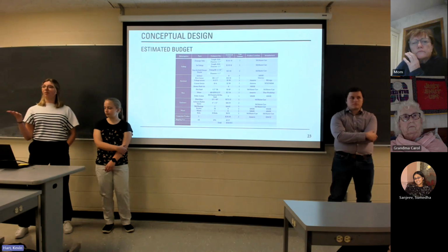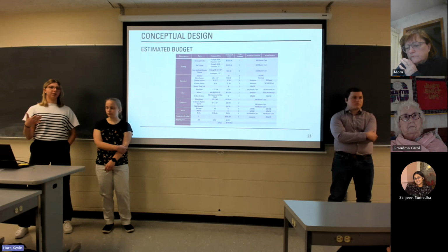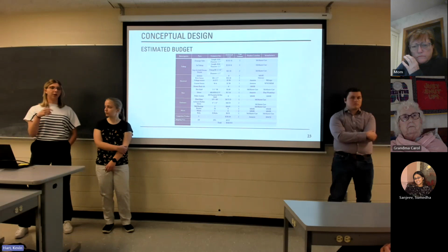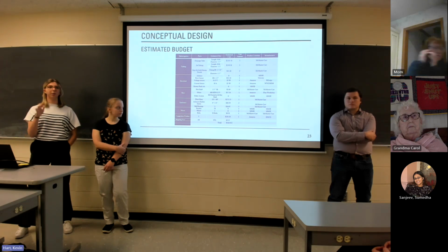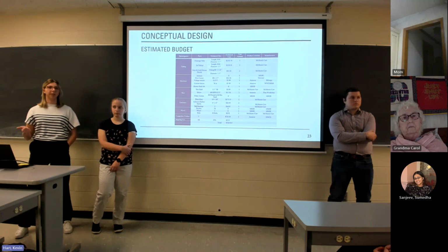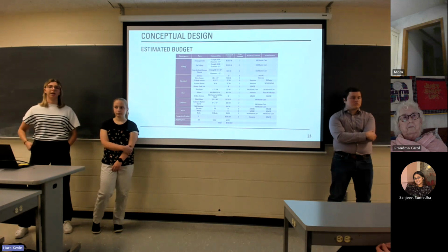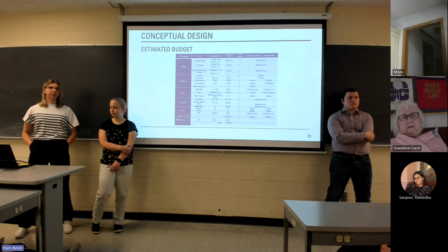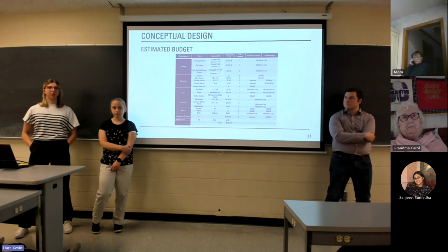However, we do not know what that's going to produce. So the next step is CFD and FEA, trying to simulate the water jet velocity and set a number, see what number we're producing with that nozzle and whether we can actually replicate that in the lab. If we can't, then we'll go back on our design, see what diameter we need, how many buckets, and if that works. And if not, we'll up the size or lower the size. But as of now, we think the 7/8 will fit and do the job.